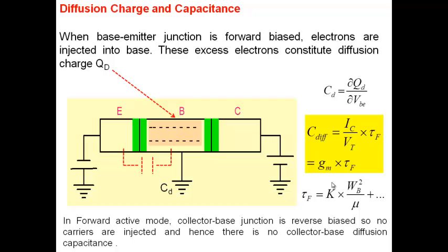Note that only if I don't have a capacitance in my system will everything respond instantaneously to voltage. As basic elements, you have resistance, capacitance and inductance. If you have only resistances in your system, then it has infinite speed. It responds instantaneously to any change in voltage. It's only when you have a capacitance that you can change the voltage and the current does not respond instantaneously. It takes time. So the reason why a transistor has a finite speed is because it has capacitances. And the smaller the capacitance, the higher in general the speed of the transistor.